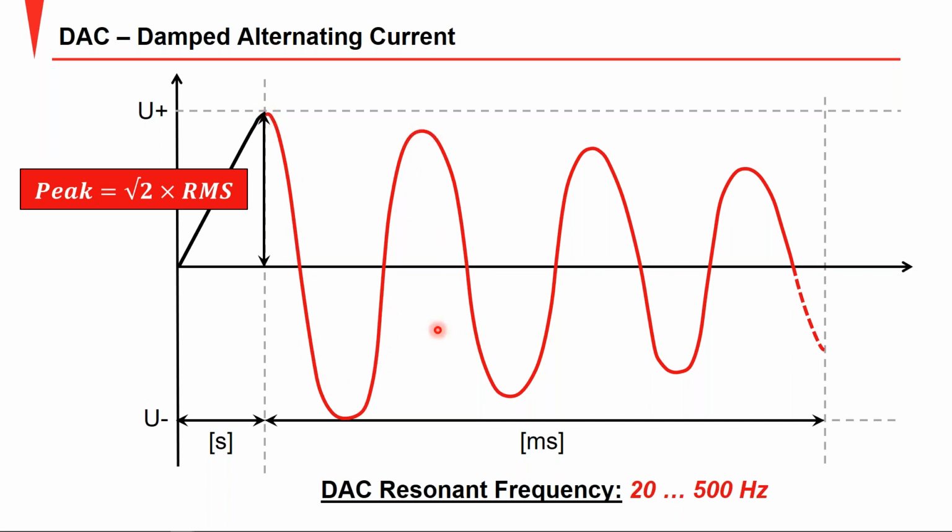And this is really ideal because it is not only comparable to power frequency results, but it has its certain application. You can tell that it's a finite millisecond wave, as well as a decaying wave, in which most of your partial discharges are going to take place in the first period where you have the higher voltage. What this does is allow you to perform partial discharge diagnostics comparable to power frequency while not applying a constant load to the cable.